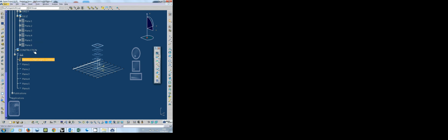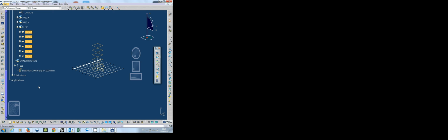And give me plane 1, 2, 3, 4, 5, 6. Notice the name is identical to my original object, right? So therefore, there's one tip that you can rename them. If you remember, by using the Excel data sheet. So I select all those names, right? I click this Excel data sheet. This is the one which is used to generate a spreadsheet, but we can use it to quick rename as one group, in one go as well.